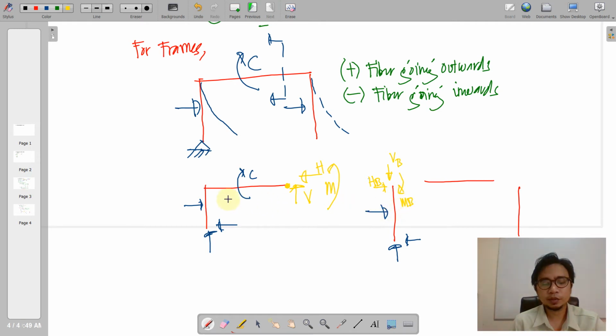So of course, if it is a frame, usually it has three components or internal forces developed depending on the loading. Of course, if we have a horizontal load, it will include now a horizontal internal reaction on that. So if we are going to assume a horizontal HB here, it would be the same horizontal HB on this beam here. However, it will be oppositely directed when it is transferred to the member.